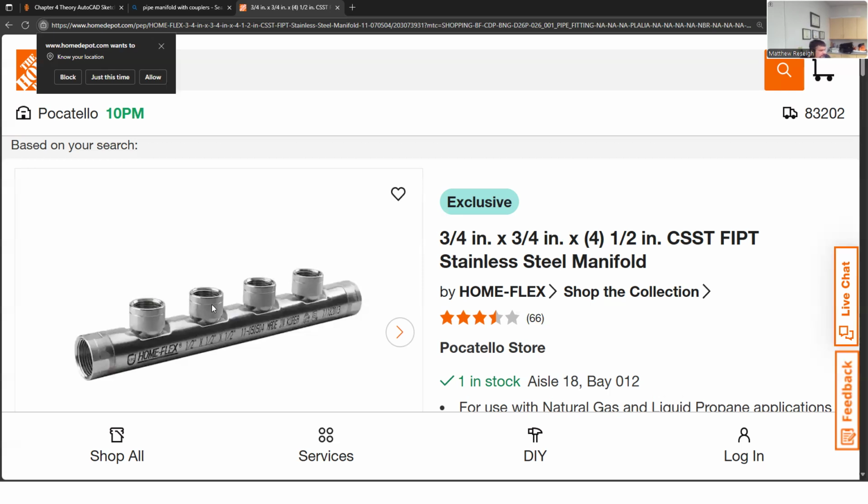If we go back, I just want to show a quick thing of what a spot face might look like. It's machine work to accept maybe a fitting of sorts, and it helps alignment. If somebody spot faces something and this pipe's already spot faced, I can almost, without measurements, just come back and put my couplers on there real quick and weld them all out.